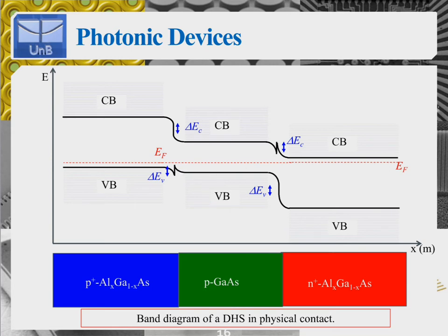Now notice that in all of the junctions you have the S-shape bending of the bands, so looking like this, the upside down parabola and the right side up parabola. In all of these junctions, this is the behavior, but the discontinuity that is there, or the potential barrier, is still the same, right? It's still right at the center here of the bending.